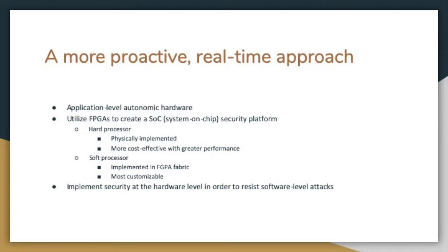The hardware design discussed in this paper can both monitor and possibly override software operations in real time at the lowest level, so at the I/O pin level, of a system-on-chip platform containing a microcontroller with configurable logic. By synthesizing the solution into hardware, it can also resist software reconfiguration attacks.